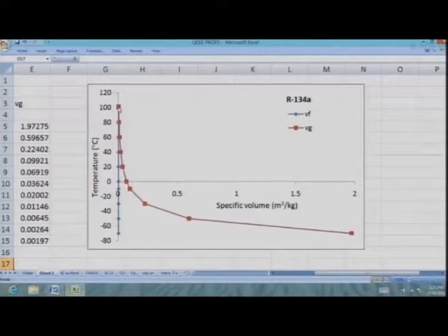But when we go to the saturated vapor state, we see this line coming here. And you can see a very large change in the specific volume, something which was like 0.001 or 0.002 of that order has now become at least 100 times bigger. It's now 1 over here and goes up to 2. So the first thing to note is that in many of the cases, there's a very large change in specific volume that accompanies this phase change process. Water at ambient conditions, when it changes phase from liquid to vapor, its specific volume increases by almost 1,000 times. So there's a huge increase in volume that takes place.